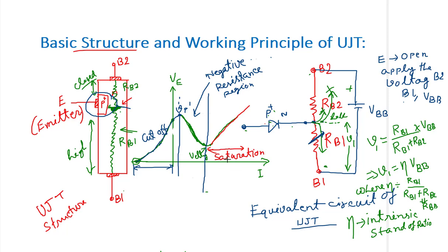Both voltage and current increase together. For this region, VE is less than V1 plus VD, where VD is the diode cut-in voltage. That is the cut-in voltage.